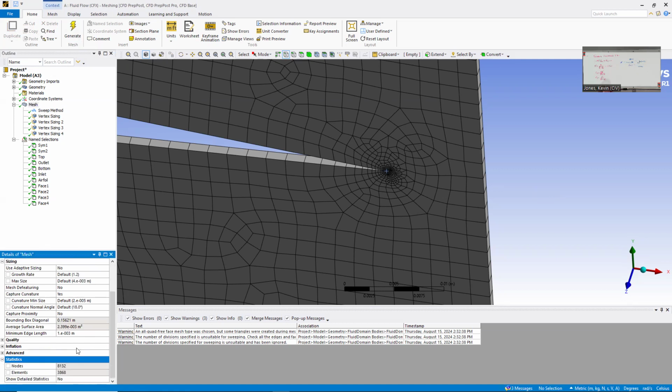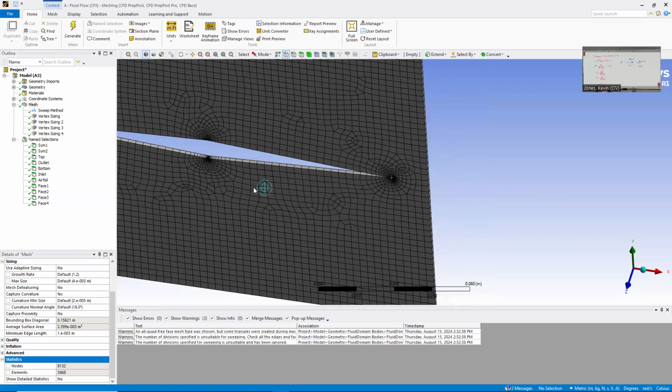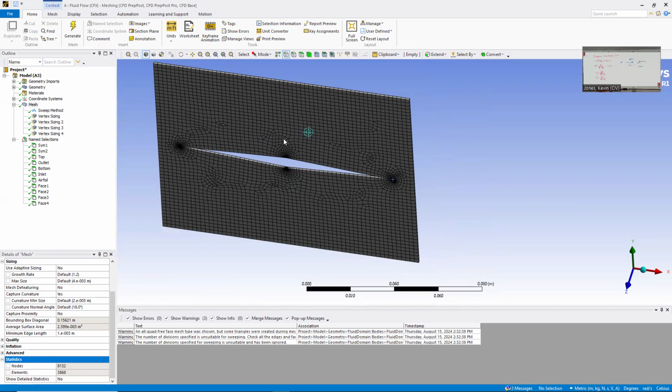I think if you do it the nominal length, it's like 23,000. I think I've gone up to maybe a meter downstream. The main punishment when you make it long is when you start to do the refined mesh. You need to have a lot of points at the end, so it gets progressively slower and slower to compute. All right, so that should be good.